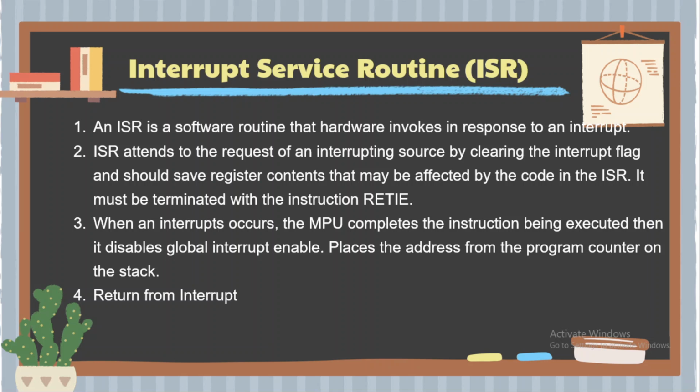by code in the ISR. When an interrupt occurs, the MPU completes the instruction being executed, then it disables the global interrupt enable and places the address from the program counter on the stack.